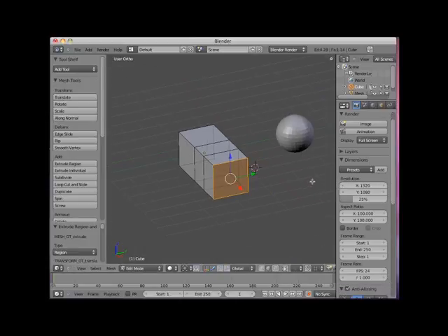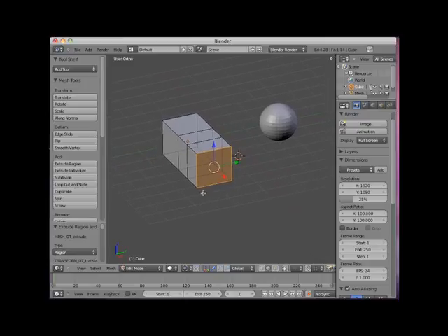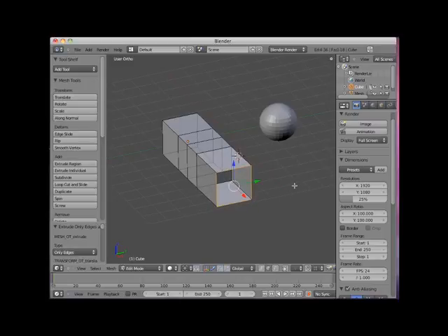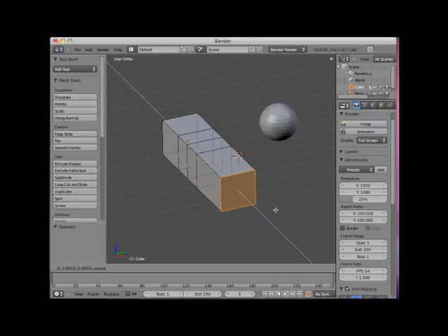With the new face selected, I'll press the Extrude Individual button. Note that instead of extruding the influenced face, just the 4 edges are extruded. Also, because there is no face normal, the extrusion is set to grab mode, and I can place the extrusion anywhere by left-clicking. I will undo this last extrusion. With the 4 edges selected, and thus the face implicitly selected, I'll press the E key again, and as expected, the face is extruded and constrained to the face normal.